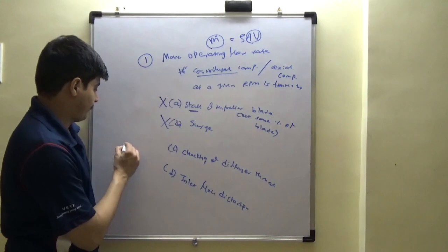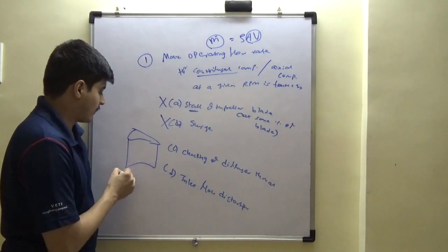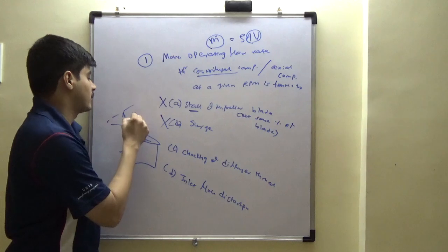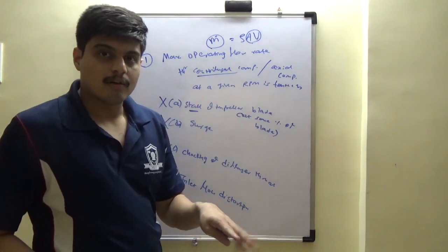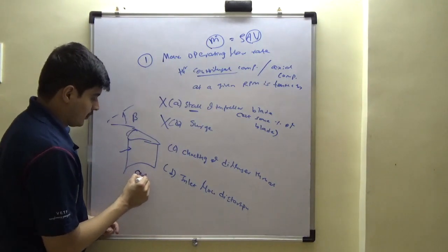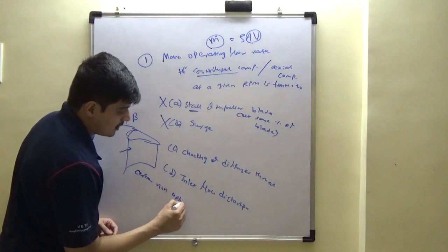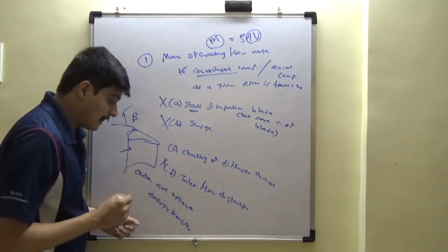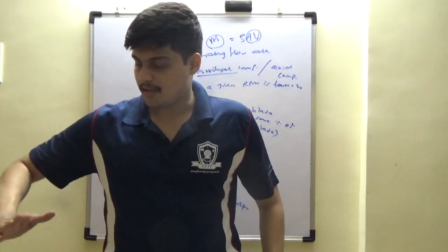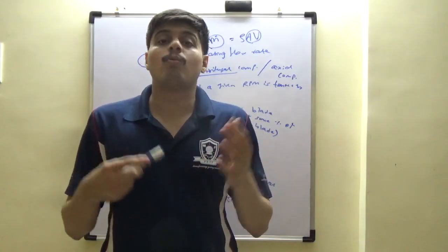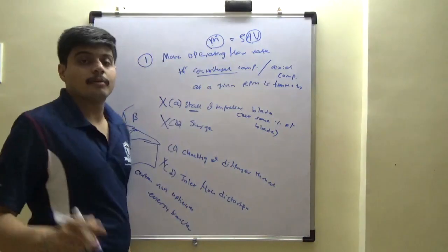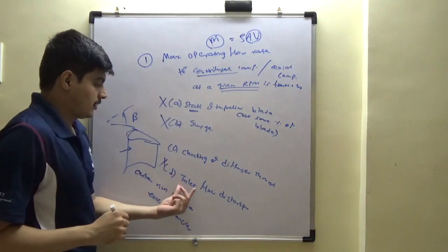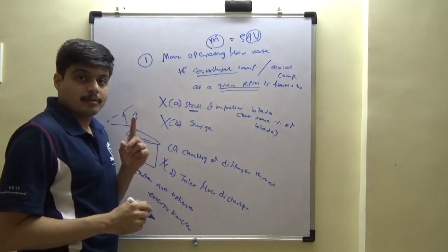Inlet flow distortion. This is the blade, may it be of axial or centrifugal. The flow is getting directed at certain angle, theta or beta. Distortion would cause certain non-optimum energy transfer. But again, this is not the driver. Distorted flow would produce lower specific work, but not minimum operating condition. Because at a given RPM, most important, this distortion would reduce it, not significant.